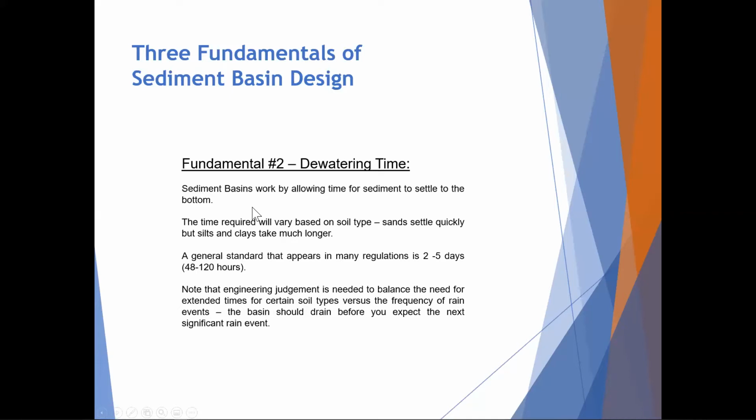So the next fundamental is dewatering time. So as we talked about before, basins work by allowing time for mud to settle. So the time needed to settle is going to depend on the soil type. So sands will settle quickly, but silts and clays may take much longer and often may not settle at all for weeks. But a general standard that we see in many areas is 2 to 5 days.